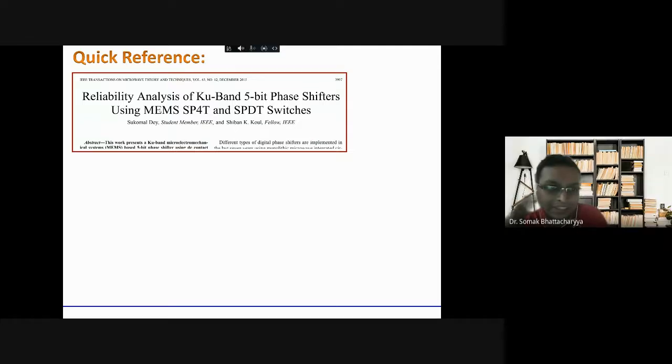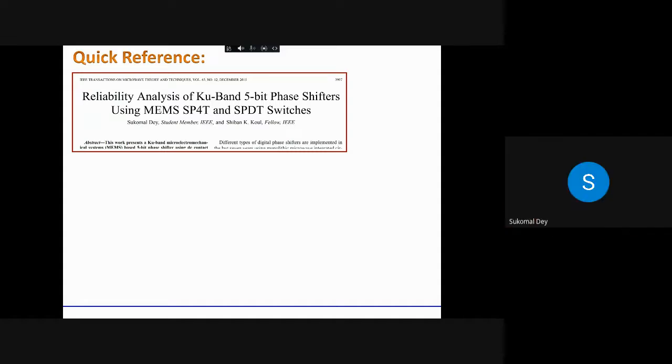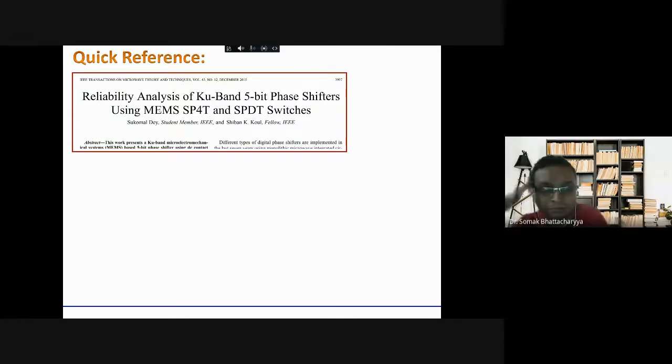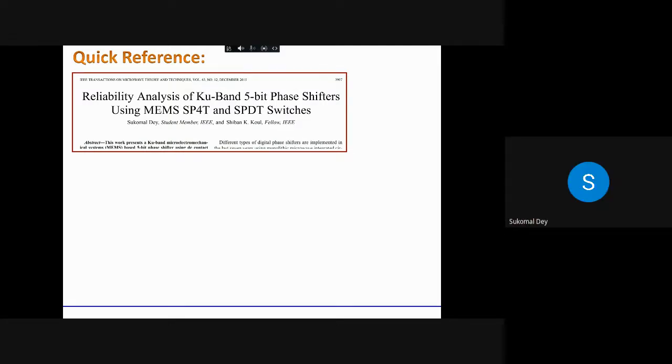Doctor, I have a question. What is the typical power handling capability of these devices? If you ask me at the current time, it has already reached up to 5 watts of power. Oh, it's huge. Yeah, 4 to 5 watts on a conventional coplanar waveguide, CPW, version. But if you use 3D micromachining, if it is a waveguide, then you can substantially improve the power. Sir, in the VNA it is up to 1 watt or something, so it is taking the power from the VNA.